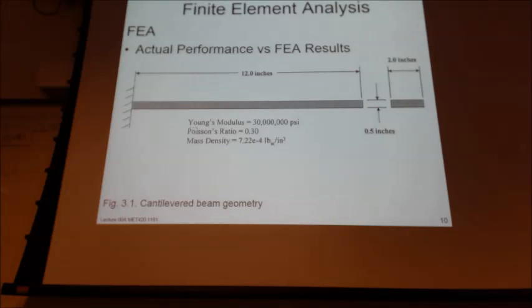The positioning of the material, I mean, we're assuming that that is square to the load, square to the mount. We're assuming that the cross section is orthogonal, and maybe that's not the case in the real world. So there's another source of error. So even this pretty simplistic problem can present lots of error and places where the FEA is going to differ from what's actually happening in the real world. So that's part of why we say the pretty pictures are always wrong.